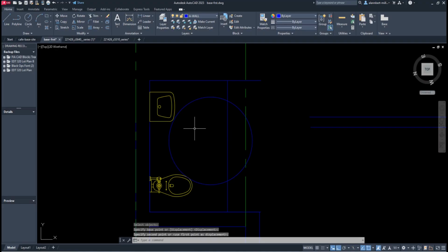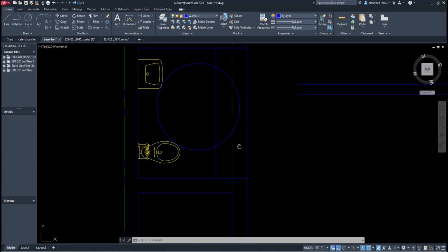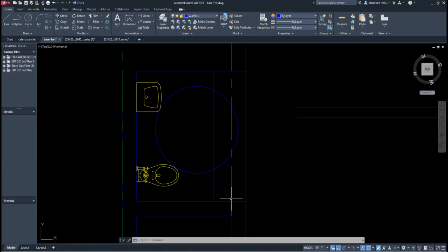Now this one's a give or take because we can overlap, not by 12 inches though. So let's see if we can open it in here. So this line now becomes the line of my wall. So I'm going to continue there. And then this is a 10-inch CMU because this is the elevator shaft. And this one is just a chipboard wall. So what I'm going to do is offset by 7 or 8 inch. So I think we use 7.